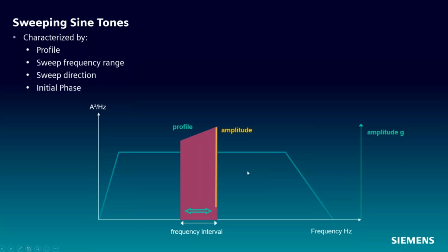This is indicative of an engine that changes speed. For instance, on a propeller aircraft that's able to change how the propellers move, you'll see this phenomenon where you have all these sweeping sine tones superimposed that are the primary engine frequency and then the blade pass frequencies, and they can sweep up and down to simulate the engine changing RPMs. We'll take a look at that in the software too.